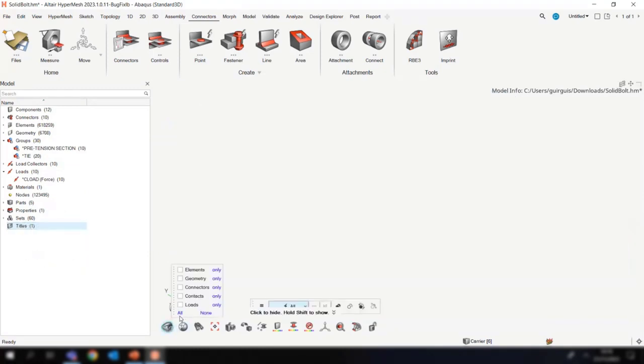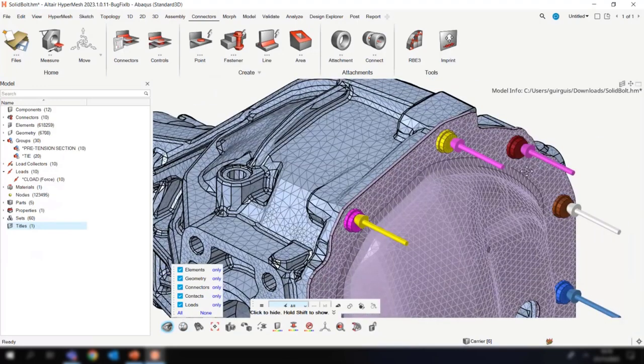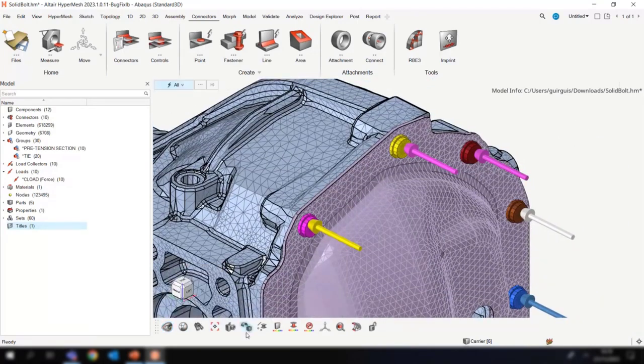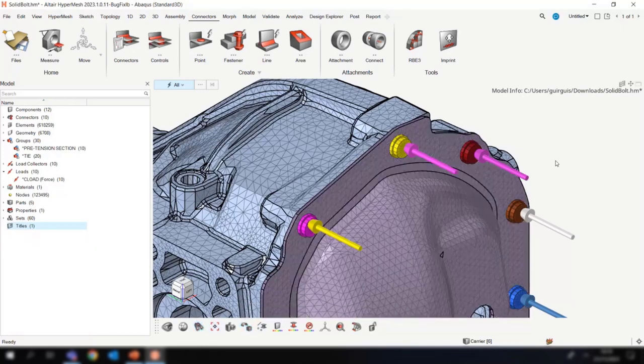If your final layer is a shell element, we will not generate a threaded contact. It has to be a tied contact, because a threaded contact on a 2D shell doesn't necessarily make sense, especially if it's planar, like that classic 3-plate model. You're not necessarily going to see the contact making much sense in that case.